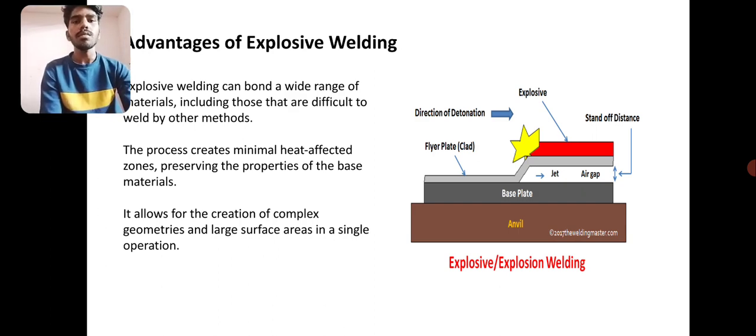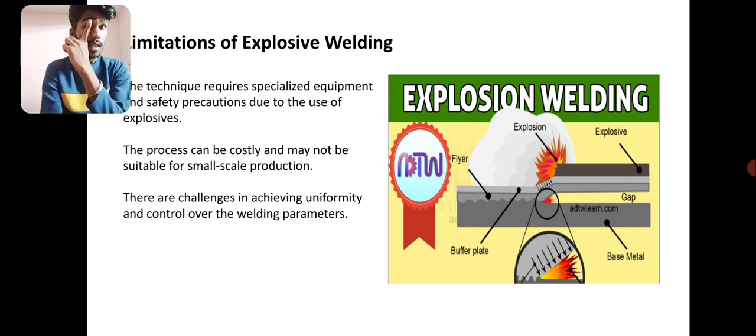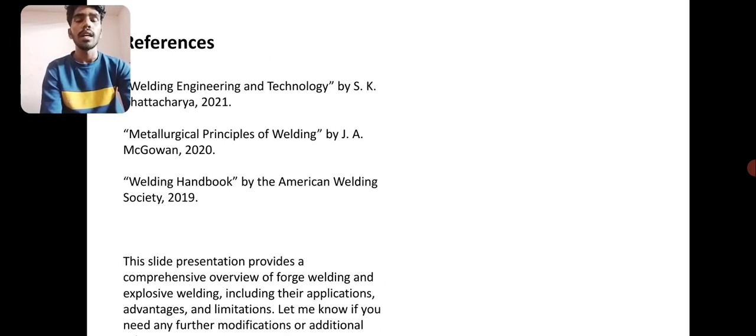Limitations of explosive welding: the technique requires specialized equipment and safety precautions due to the use of explosives. Since we are using explosions for the welding, we require skilled labor, safety precautions, and special equipment to do the welding process. The process is also costly, the cost of the equipment will definitely be high. And there are challenges of uniform control over the welding parameters.